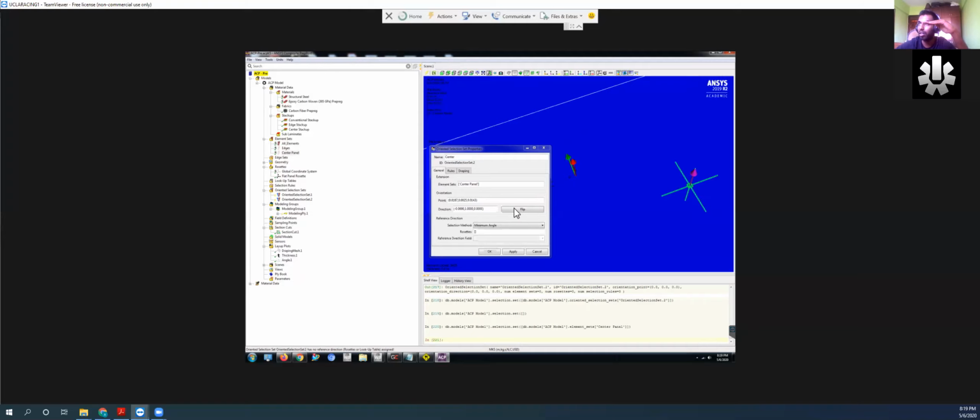And if I want it the other way, like let's say I want to build downwards, then I have to flip the arrow. So if I click flip, the arrow points downwards, then it means it's going to build this way instead. So I want it to flip upwards, so it's fine. Selection methods, leave it as that, and then under rosettes, click between the brackets again, and then choose the rosette that you created earlier, which is flat panel rosette. And then you want to just press OK.